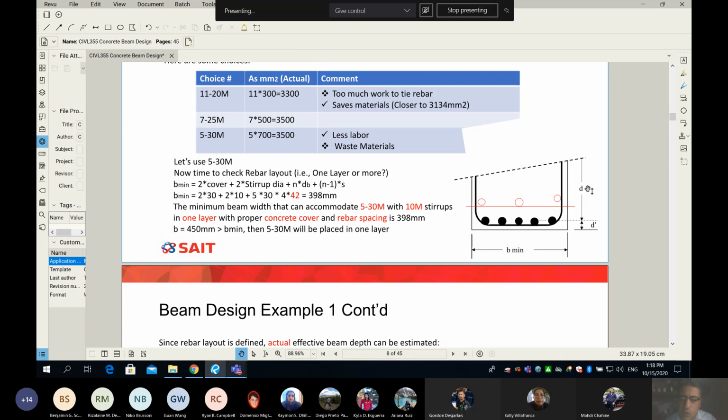This is very typical in walls, I'm talking about frost walls, because in walls there is no stirrup at all. And how do we hold rebar in place? There are so many ways, to be honest. I've seen so many ways on site. Some people use wires and some sort of cross member like wood, and then they tie the top bars to the wood.